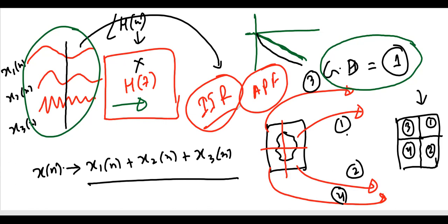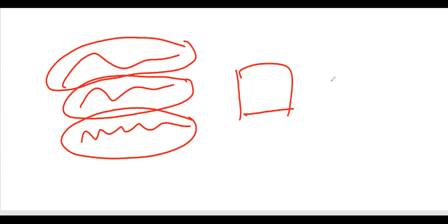The fundamental thing is that if we have different frequency components in a particular signal with nonlinear phase responses with respect to each other, then after filtering it is very difficult to match these 3 frequency components together to retrieve the original signal back, and that makes a problem.